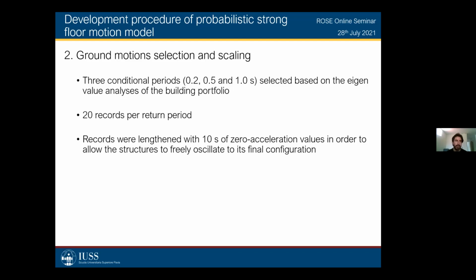many of you probably know already, when you perform a nonlinear time history analysis of a structural numerical model, it happens almost 100% of the time that when the analysis is finished, the structure actually has not stopped moving or shaking, because this is basically just a numerical model, which means that the analysis will run as far as the ground motion actually runs.